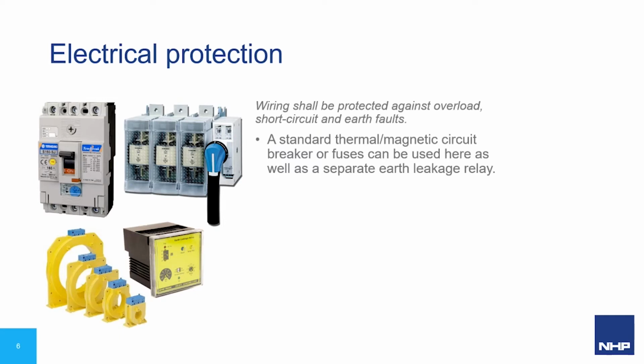Now, these devices would act to stop any short and earth fault conditions occurring, hence stopping excess heat being generated in the motor through the excess current draw, ensuring again that the surface temperature of the equipment is kept within its acceptable limits. And they would also stop any potential internal damage to the motor windings, which, if damaged, could cause further faults and sparking down the line.